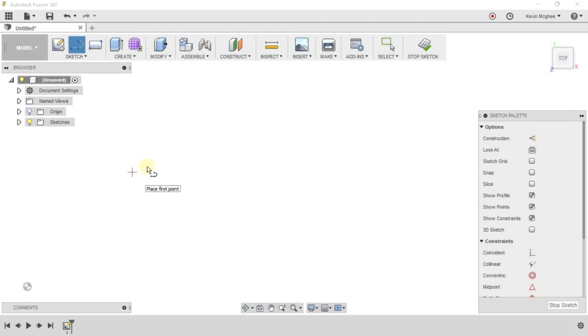And all I want to do is click and drag out a line, whatever length I want. I can just do it freely. Just drag it out, put it on an angle I want, and place it. And then when I do that, it starts up another one, and I can place it. And it'll keep asking me to do that. And you'll notice some of these little modeling aids, that blue dashed line, show up, and it's just trying to help you draw. Don't worry about it too much.